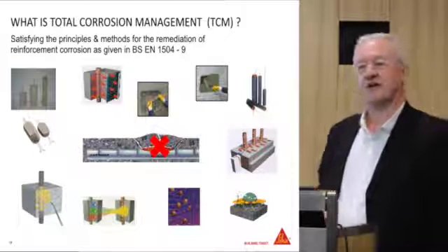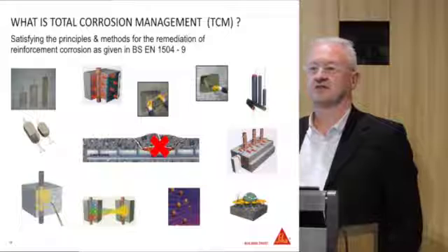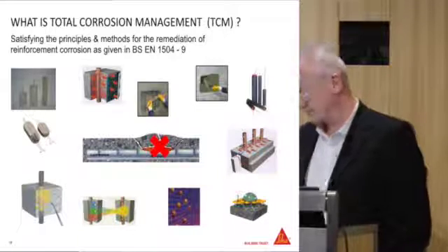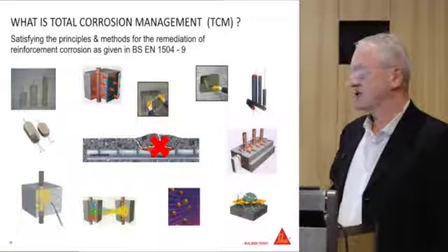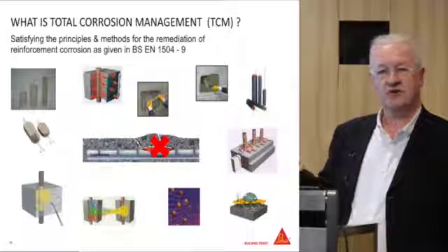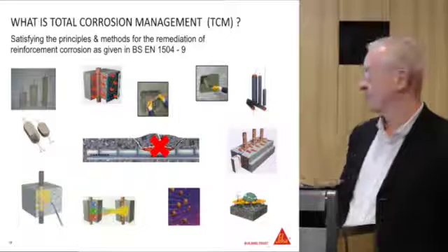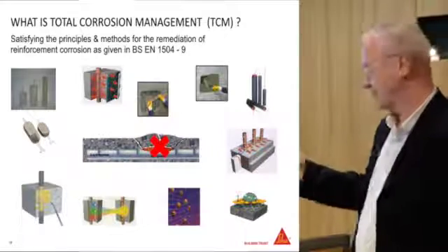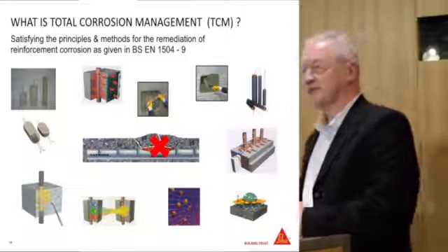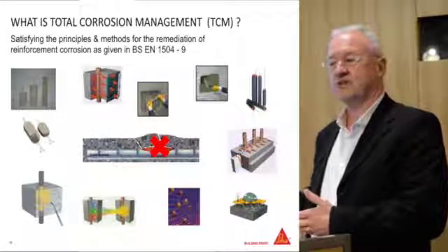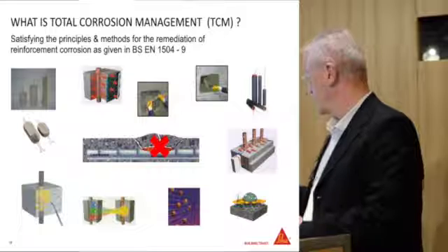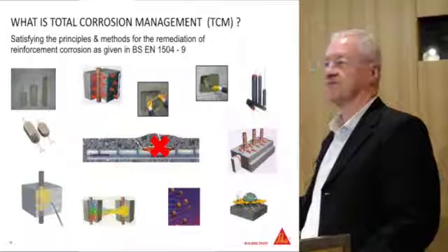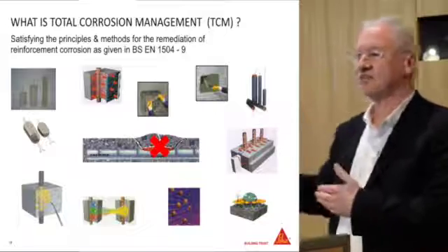looks at barrier coatings or active coatings for protection of the reinforcement once the concrete's been broken out. It also looks at the repair mortars, the R1s, 2s, 3s and 4s, but also this method gives you passivity around the bar. Then there's cathodic protection, which Chris spoke about. You can either have an overlay and a titanium mesh connected to a rectifier, and that will protect the reinforcement.